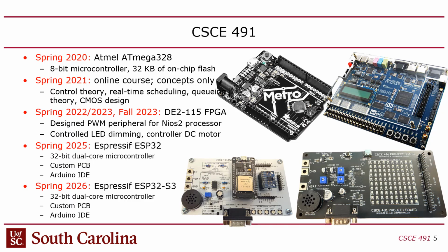But now they do. And so we switched to this ESP32, which is the next version of the 8266. And it's a 32-bit processor, unlike this guy, which was an 8-bit processor, and 200 megahertz. So it's got 2 cores. It actually does run a very thin operating system called FreeRTOS.